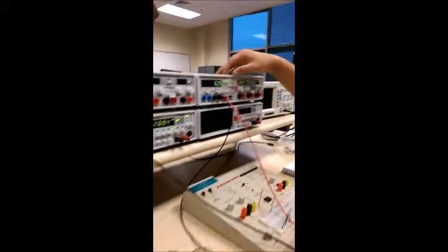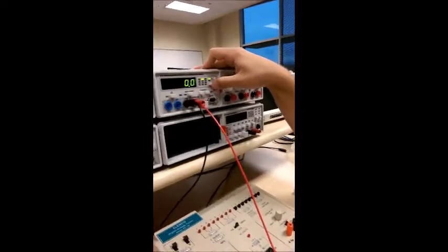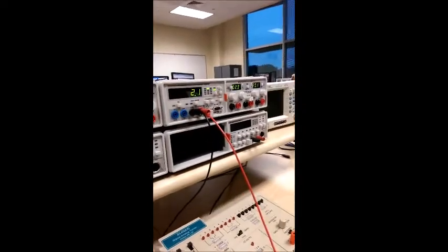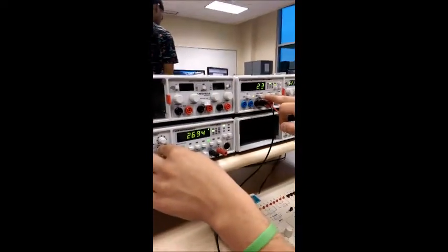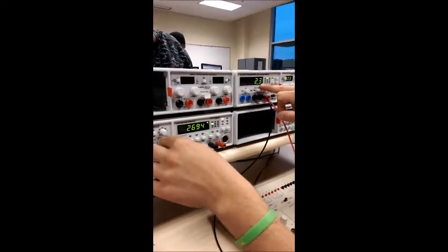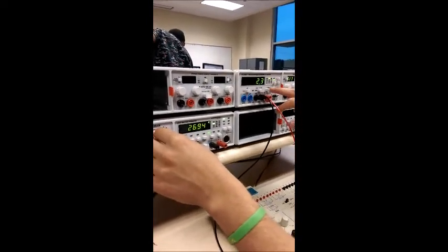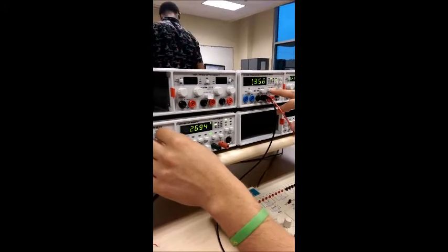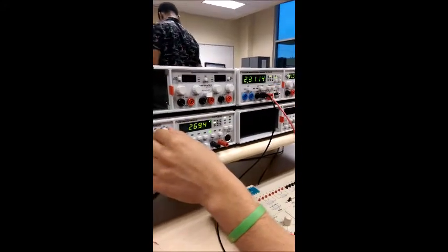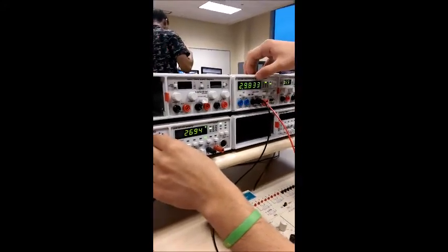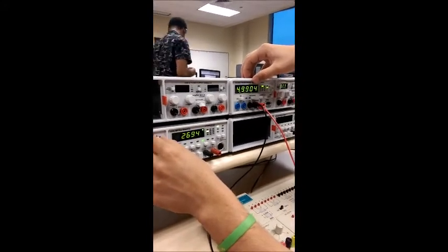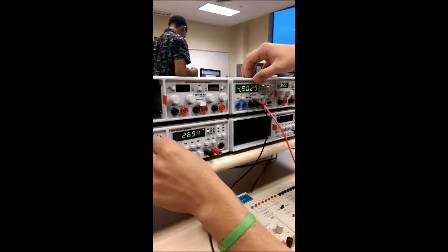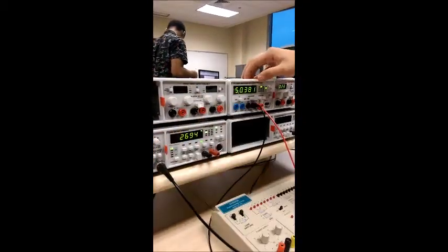And then I'm going to change the digital multimeter to an AC circuit. So I will use the amplitude wheel to change the voltage right here, until I get my 5 VRMS. First, I'm going to change the range, and I need to get 5 volts RMS here. Almost there, I got it.